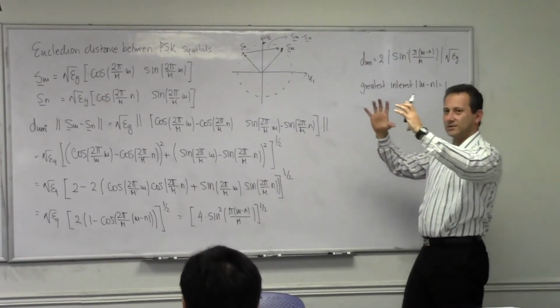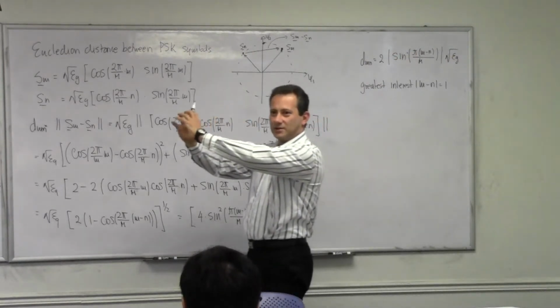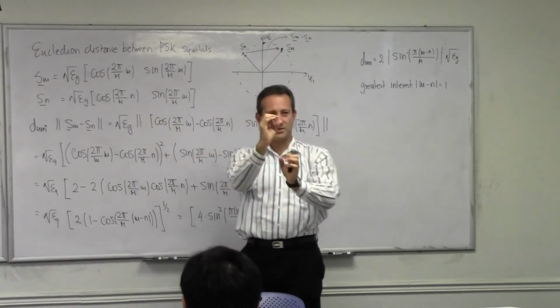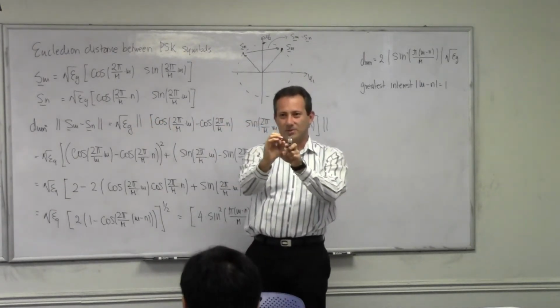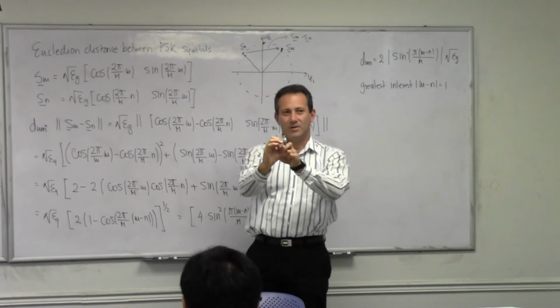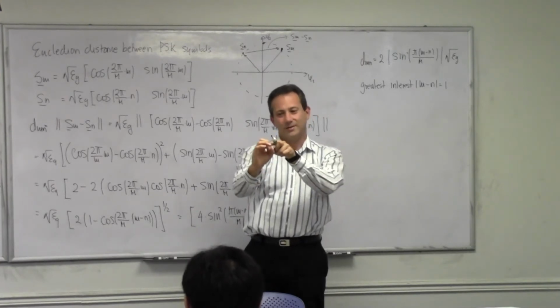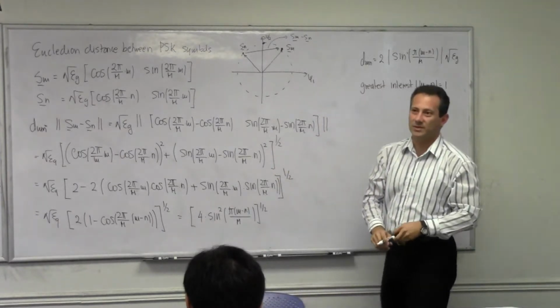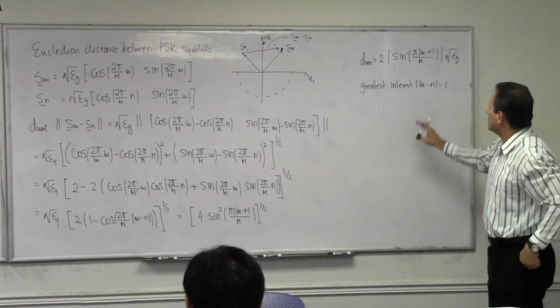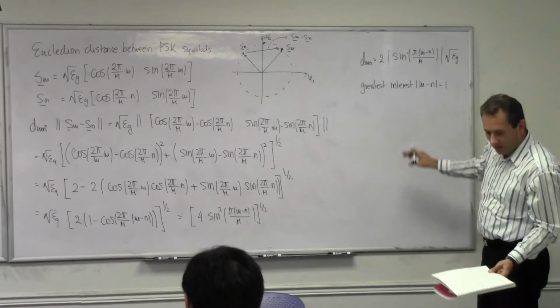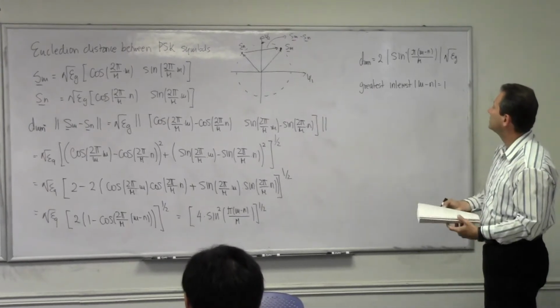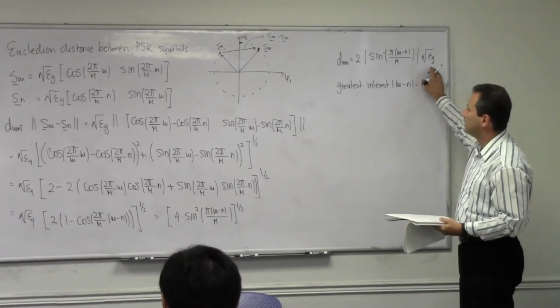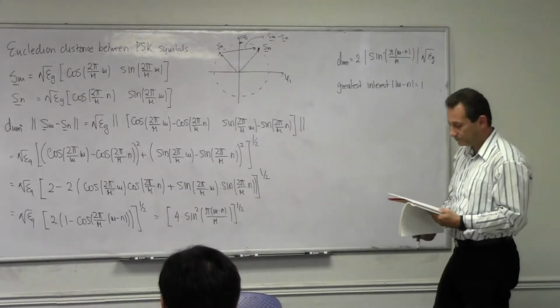But then as it travels, it kind of shrinks as well, because your energy dissipates, and then the receiver looks at the circle that's this big, and those symbols are now getting really close. And then once you start having noise, you're going to have a really hard time deciding which one of these symbols makes sense. All right, so let's take a look at what this distance ends up being for different M's.